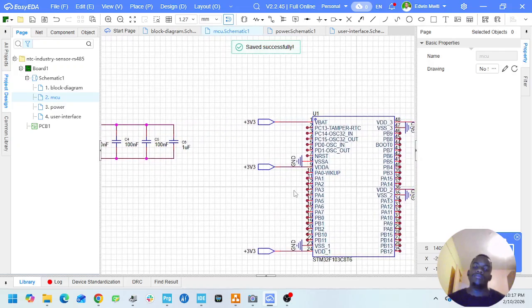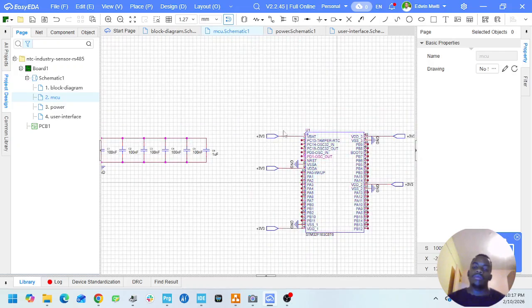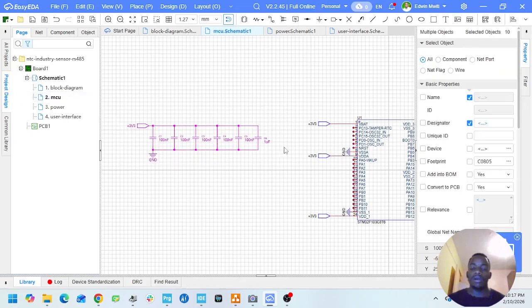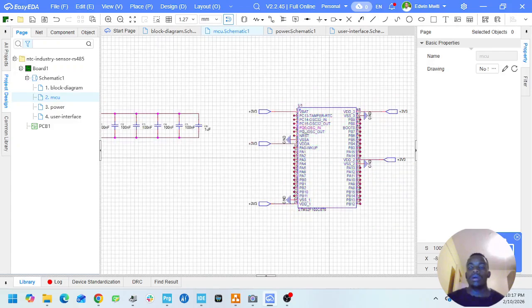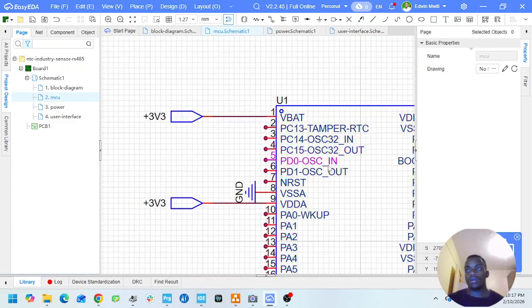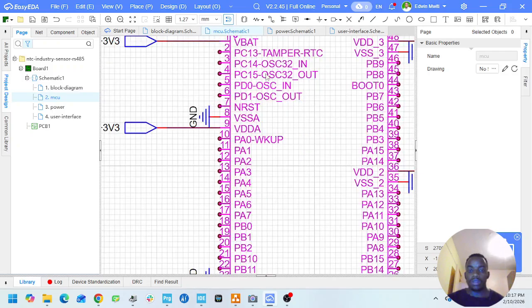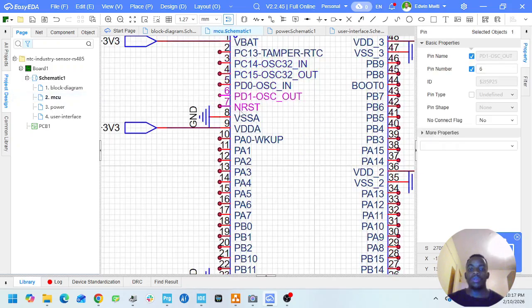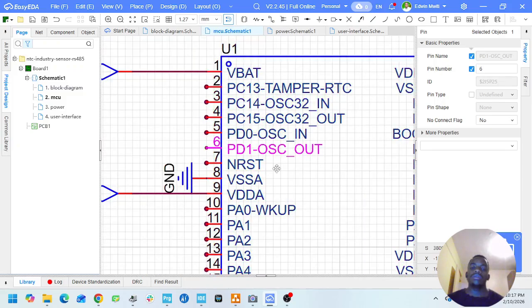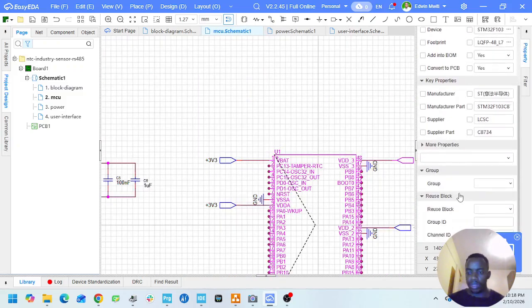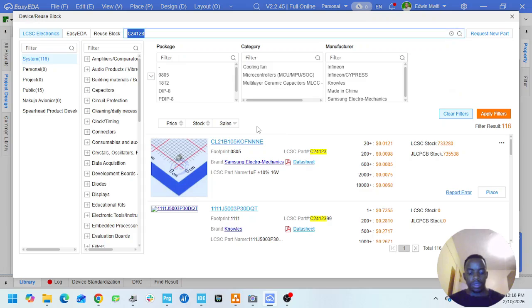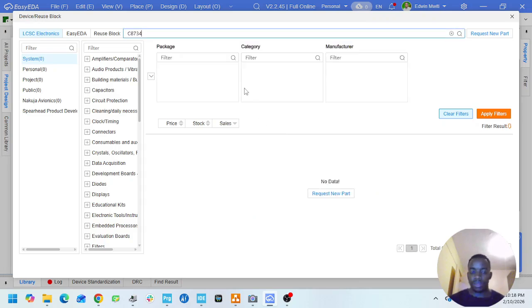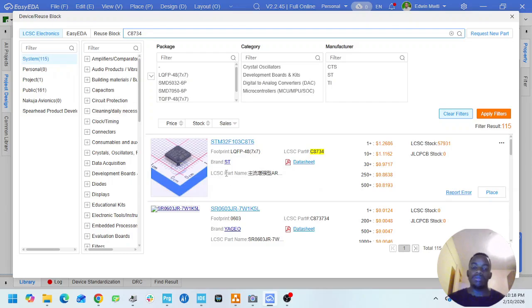So the next thing that I do, so we have the power handled. The next thing that we do is how do we add clock to this device? So there are two clocks. There's a low speed oscillator clock and high speed oscillator. So I like to use 16. This device, if I open the data sheet should be somewhere. Should use 16, but let me just confirm that it's using a 16 megahertz or a 8 megahertz clock.